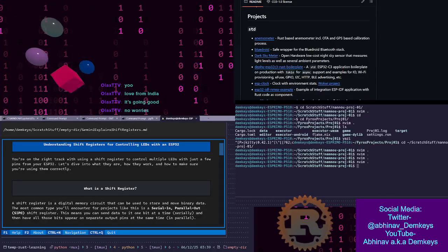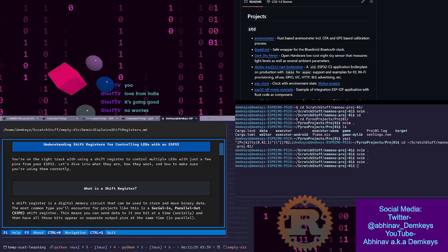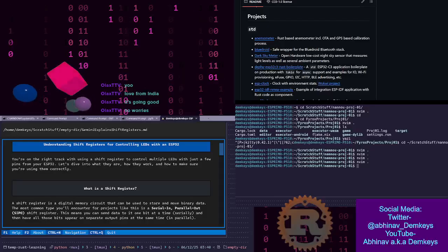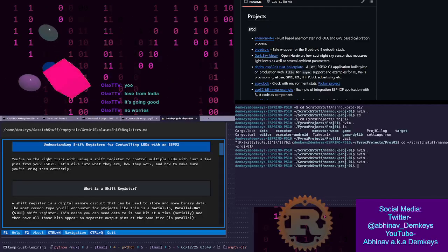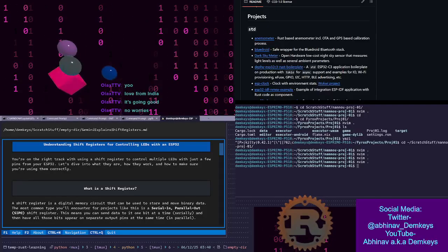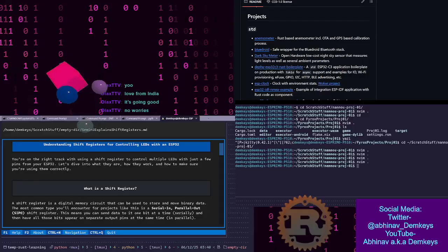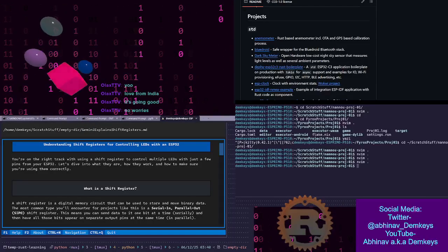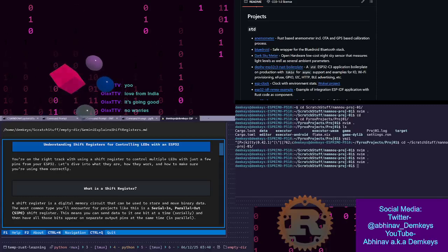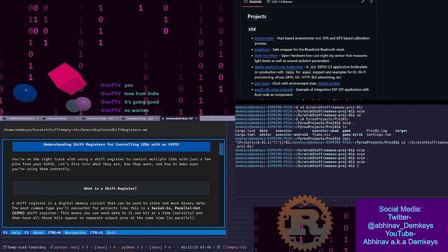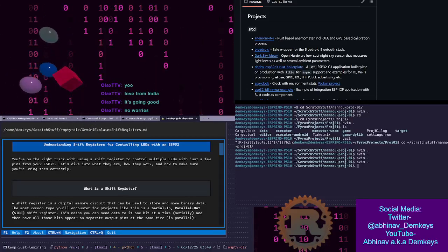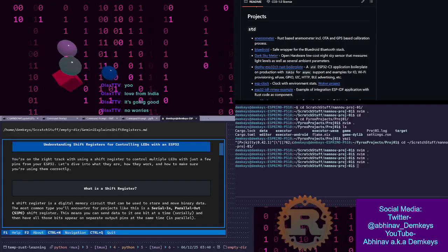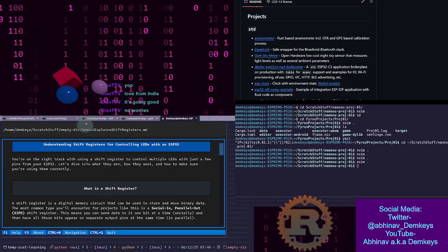One of the components there, I could see it wasn't soldered properly, because of which there was a bridge between that component and another component. And so I knew if I connect this, it's not gonna work out well. Fortunately, I did order a couple of other MPU 6050s, so I will be able to use those whenever I do get to it.